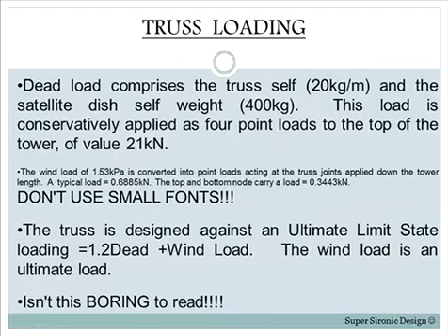So it was a square tower. And each of those point loads added up to 21 kilonewton. Now in their case, they didn't have a live load, they had a wind load, a horizontal wind load of 1.35 kPa, and that was converted into point loads acting at each joint as you move down the tower. And the typical load was 0.68, and at the top and the bottom, because of the smaller contributing area, it was half of that, 0.34. Now I assume you all know what I'm talking about, even though you haven't seen the structure.